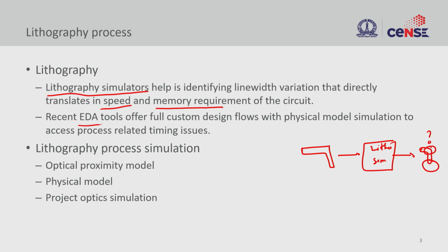And when we say litho process simulation, this could be related to optical proximity correction, right. If you have a line close to a particular structure, and you want to have a certain clearance between these two, and you also want to look at these edge effects, we can run an optical proximity model on this particular design, and the model will tell you where to add features or reduce features to counter your proximity related issues.